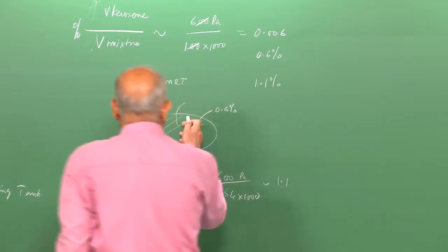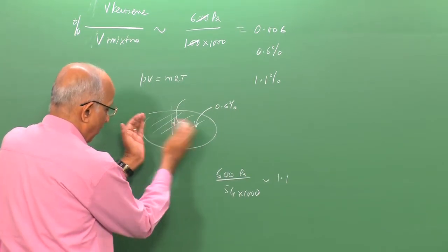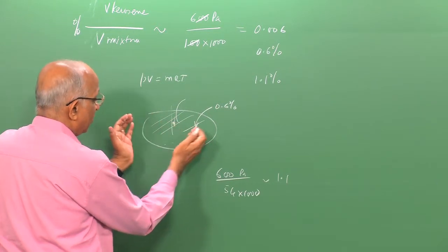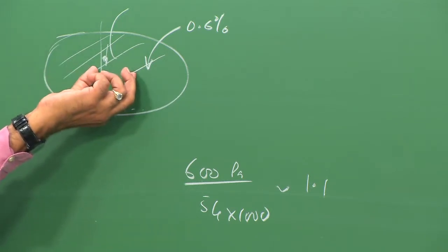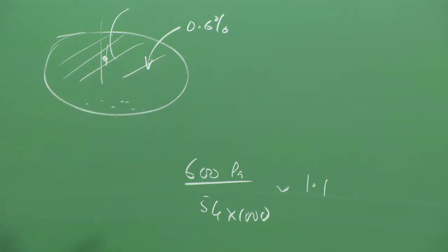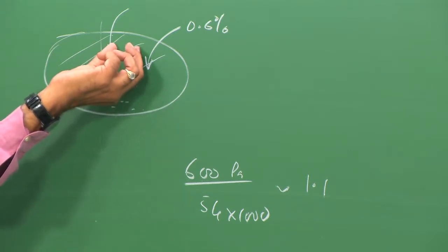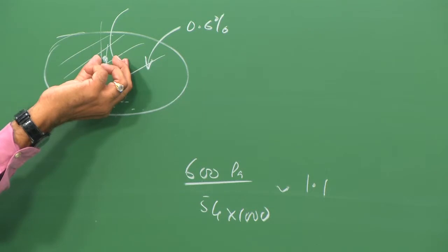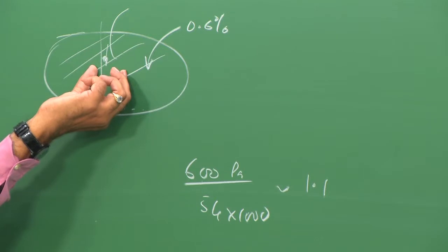That means you have a flammable mixture. Because of the spark which is generated, I could have a flame or a combustion, and I have energy release, and this is what causes the rupture of the tank. But we will do this problem again when we talk in terms of confined explosions to be able to calculate how much pressure is generated. But for the present, from what we learned about the lean flammability limits, we are able to tell ourselves, well, at altitude, when the ambient pressure decreases, I can form a mixture which is flammable, and therefore, there could be a catastrophe. And this is what happened in this particular flight.